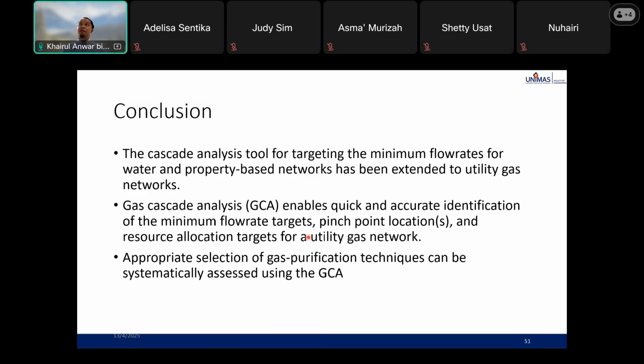For the case of gas, you can actually reuse or recycle. The difference between reuse and recycle: check Figure 5 in this paper, page 5990. The recycle here for process one, the pinch occurs at the source 10 kg per second, 40%. So the recycle means it's going back to process one at 3.57 kg per second. The reuse is actually going to other processes.